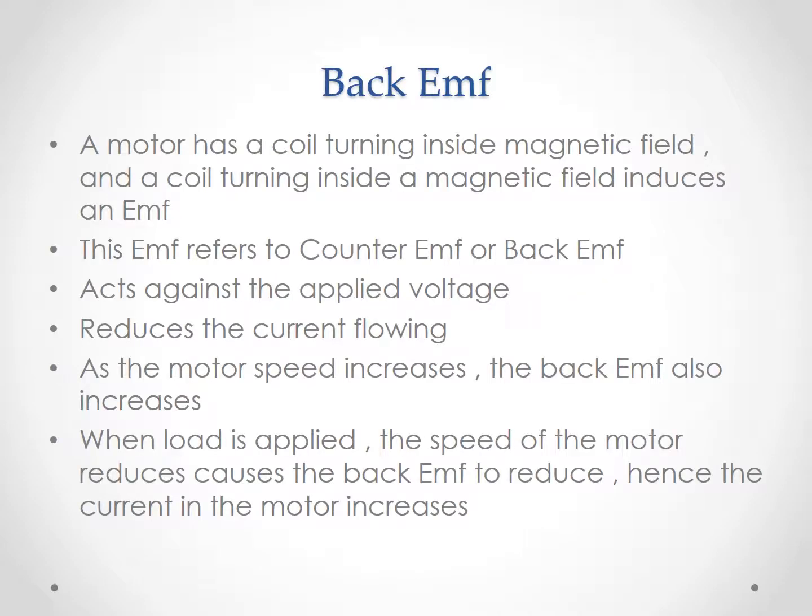Okay, next I'm going to talk about the back EMF. A motor has a coil turning inside a magnetic field, and a coil turning inside a magnetic field induces an EMF. This EMF is referred to as back EMF, sometimes called the counter EMF.